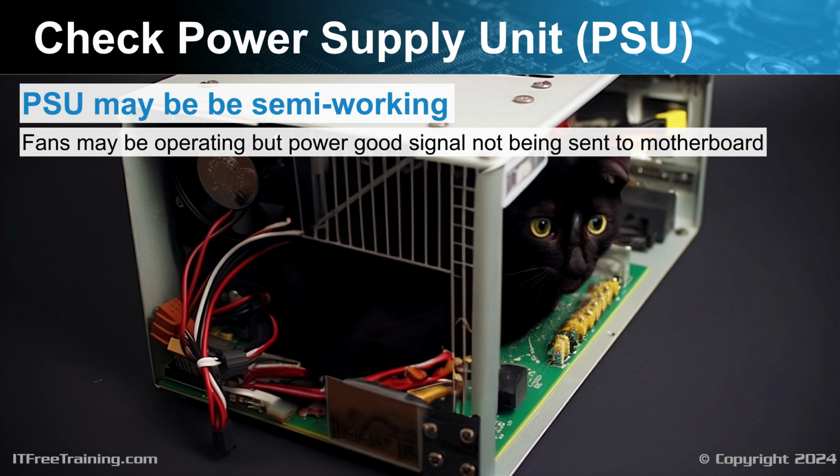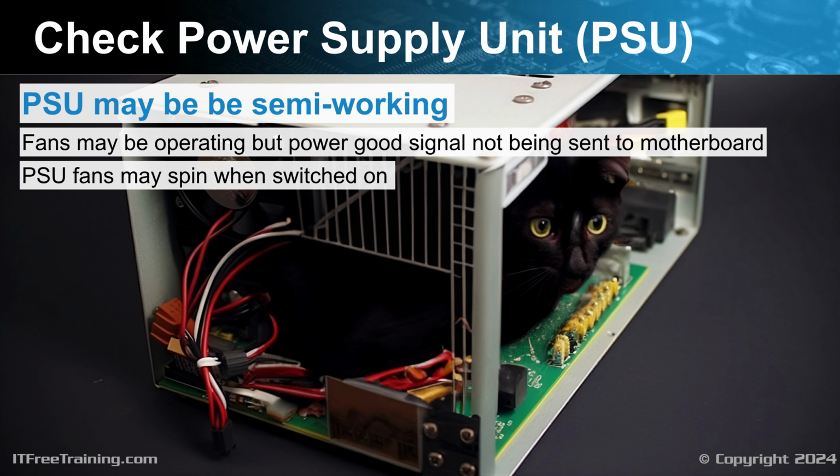For instance, the fans might be operating without sending the power good signal to the motherboard. With most power supplies, the fan spins while the power supply is on. However, some power supplies conduct an initial self-test, causing the fans to spin briefly, then stop.